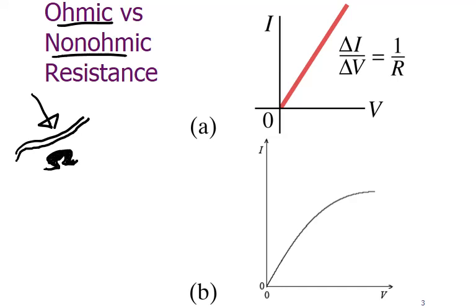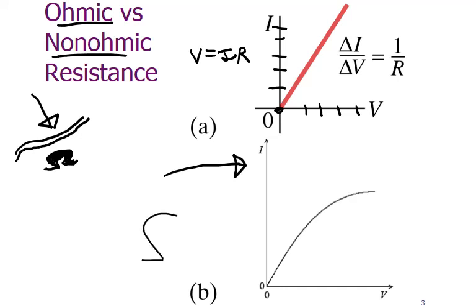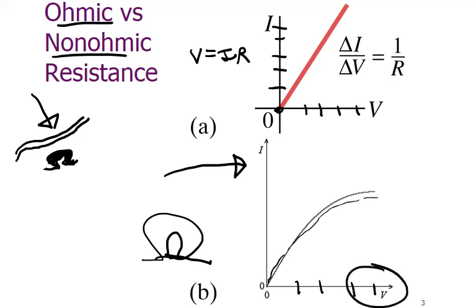Now, that follows this kind of pattern where you're increasing voltage, and current is going to increase at the same rate according to V equals IR, right? Now, this is dealing with a situation like a light bulb. A light bulb does not obey Ohm's law. As you get higher and higher in voltage, you can see how the current is actually tapering off. And so even if you go to higher voltages here, the current's not getting very much higher. And so that's important there.